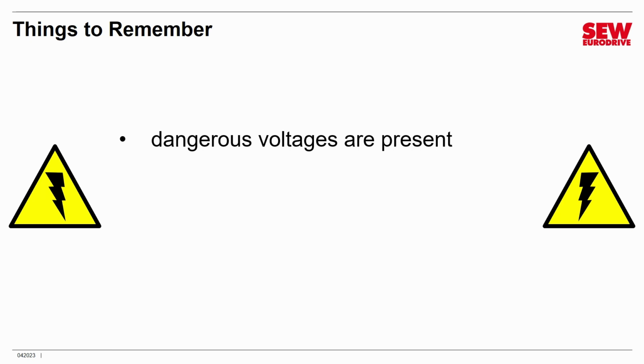If you exercise normal caution, you should be fine, but these VFDs are not toys. They are serious industrial machines. They definitely can kill you or injure you if you are careless. So treat them with the respect they deserve. Do know where the e-stop button is. If you've set up your own demo unit, then it's your responsibility to make sure you've connected up an appropriate way to stop the VFD quickly if something unexpected happens. And you shouldn't have to reach through a forest of high voltage wires.